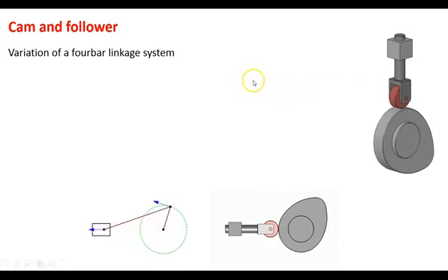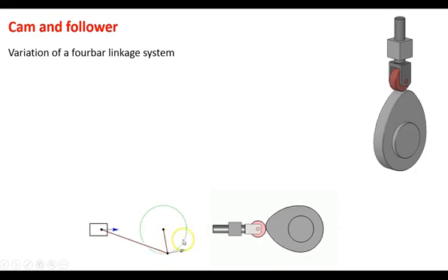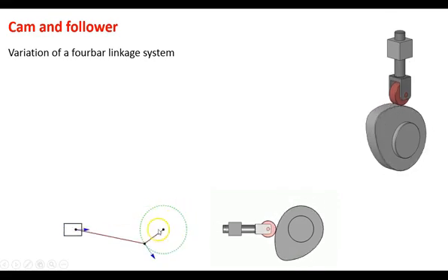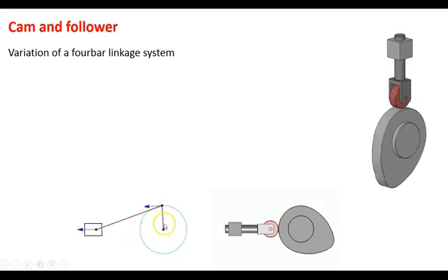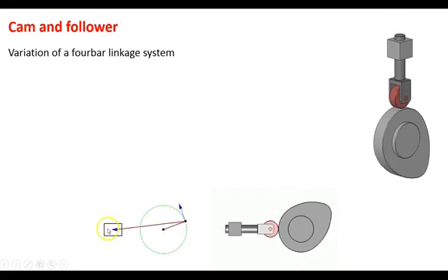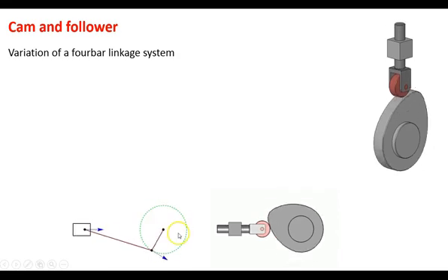Now on this 4-bar linkage, you've got the input, or the short link, that's just rotating in a cranking motion. And then you can call this link number 2. Link number 1 is the implied linkage between the two base points.